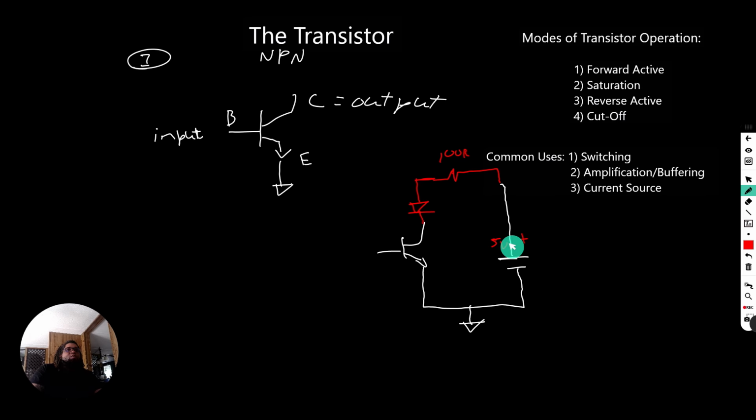This LED is connected to this 5-volt power supply through this resistor, and the resistor is there for current limiting. Remember, LEDs basically live by current. If you just hook it up to a power source, it's going to want to take as much power as is available, or even more, until it blows out, right?